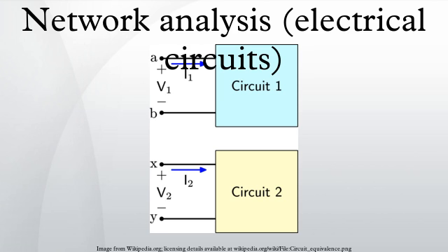It is entirely inapplicable to the DC biasing of the device. For a simple two-terminal device, the small signal equivalent circuit may be no more than 2 components. A resistance equal to the slope of the VI curve at the operating point, and tangent to the curve. A generator, because this tangent will not, in general, pass through the origin. With more terminals, more complicated equivalent circuits are required.